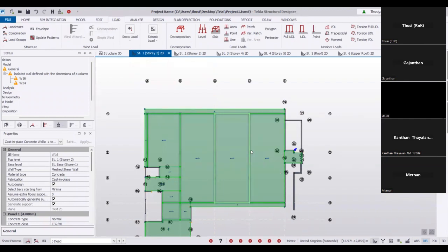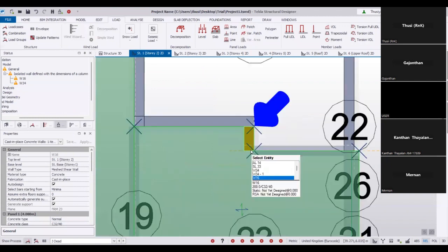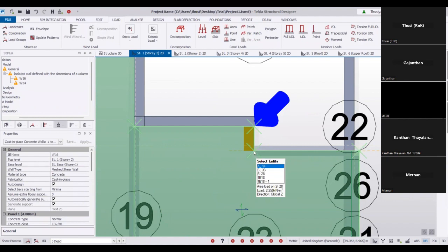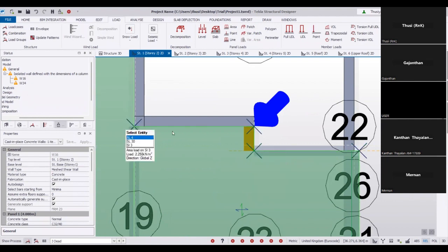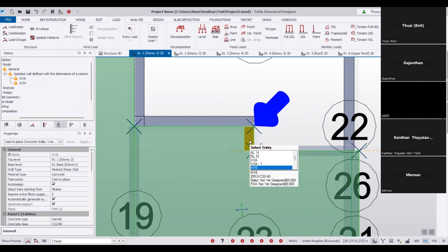So you know, a wall means the length over thickness ratio should be more than 4. Less than 4 is considered a column. But here this length is, I think, less than 4 times. That's why it is giving this warning. This is supposed to be a beam. It's not a wall, to me. Because we are going to define one group wall, we can ignore this one because this can be either wall or column.